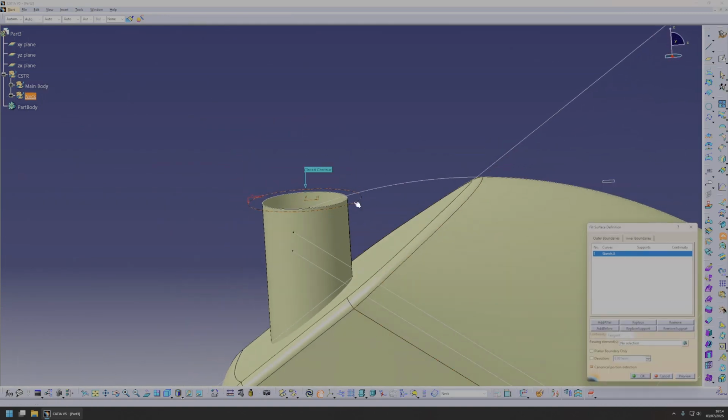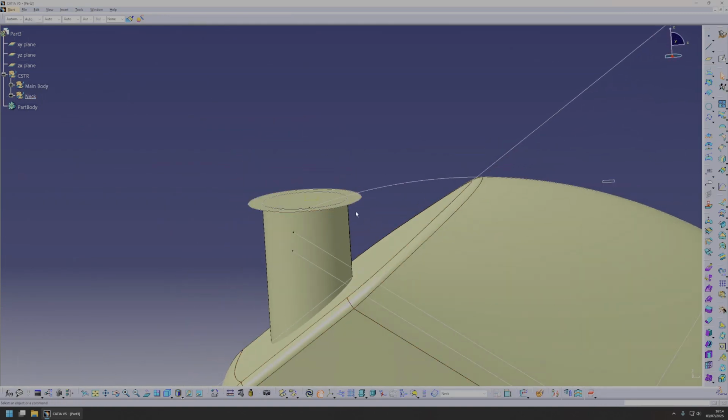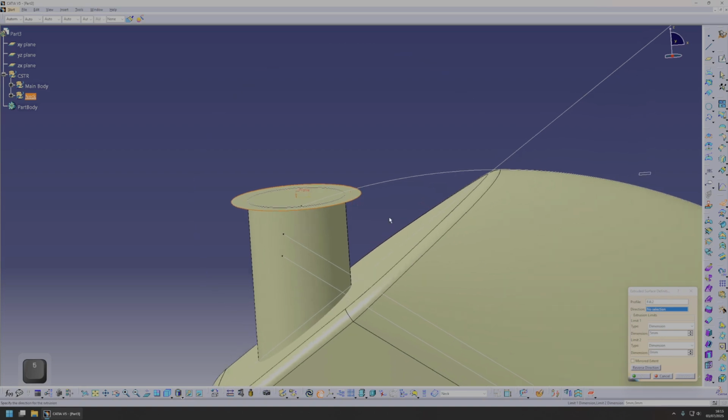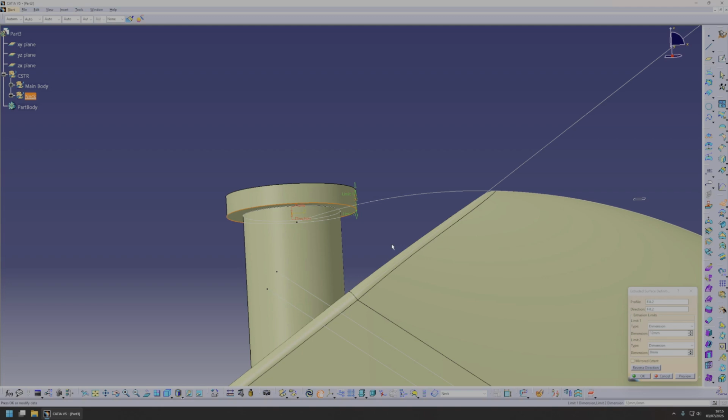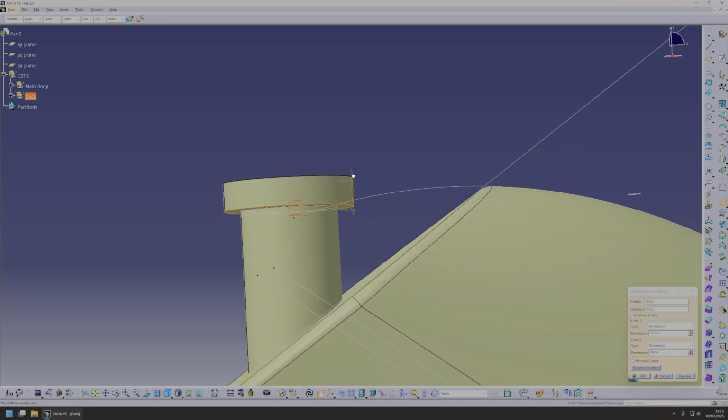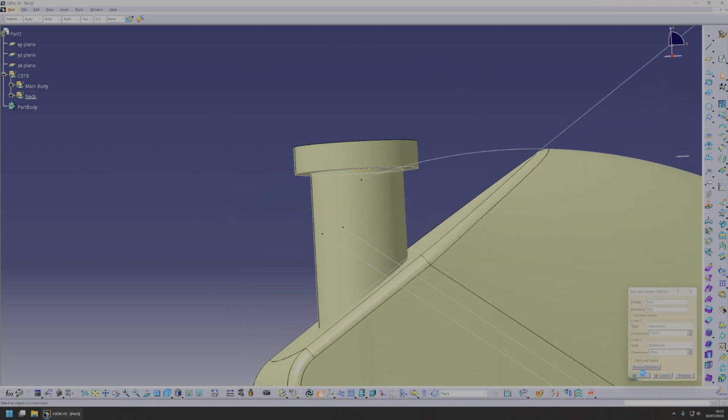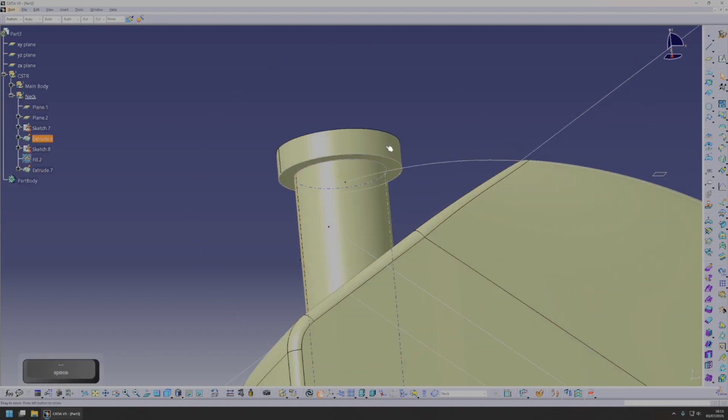And an interesting technique, just so you can have closed bodies, you can just fill this surface and extrude the surface up by 5 mil or whatever. So this then creates a closed cylinder. Then you can hide the fill, and then there you go.